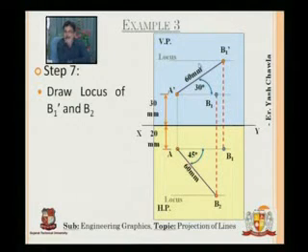So I already have the length of my plan as well as my elevation. By rotating this in this sense, or by cutting the arc, I will have the angle at which the elevation actually is. And AB1 is my plan length, and when I rotate this plan length in this manner, I will have the angle of AB, which is my actual plan.